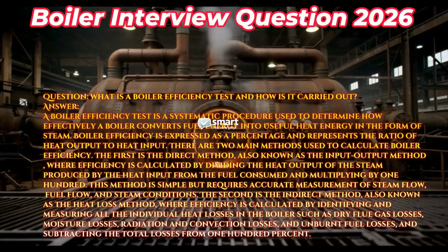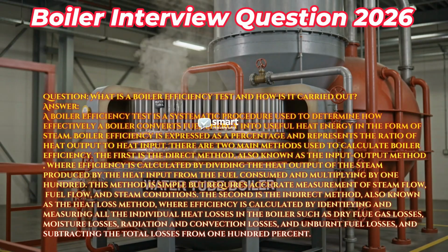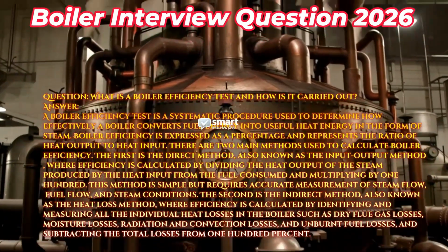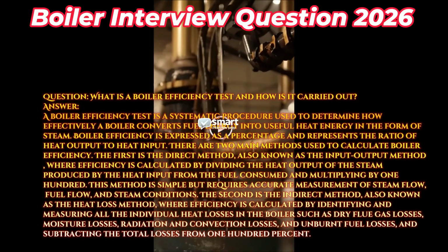The second is the indirect method, also known as the heat loss method, where efficiency is calculated by identifying and measuring all the individual heat losses in the boiler such as dry flue gas losses, moisture losses, radiation and convection losses, and unburnt fuel losses, and subtracting the total losses from 100%.